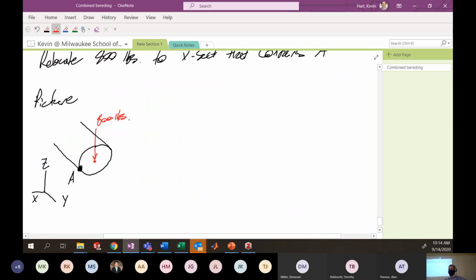Right. Now, by the force couple relationships that we know from statics, when I pick up this force and move it to a new location on the structure, I have to account for the moment that's created when I do that. So we're going to have an equivalent force couple system at this new cross-section, and I'm going to have to do something about the resultant moment that exists when I relocate this force. So my force here is pretty obvious, and again, when I talk about vectors, I'm going to put this dash over the top. So here the force in vector form is negative 800 pounds in k hat. Okay, remember, vectors need a magnitude and a direction, so negative 800 pounds in k hat.